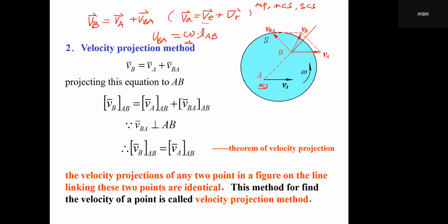So if we can find the magnitude of VBA, then we can find the magnitude of omega and its direction. From this figure, if we know first this omega with the CCW direction, and we try to find the absolute velocity, we will use this expression. First, we draw this VA. Its direction and magnitude totally equal this VA, right? Then we are going to draw VBA.